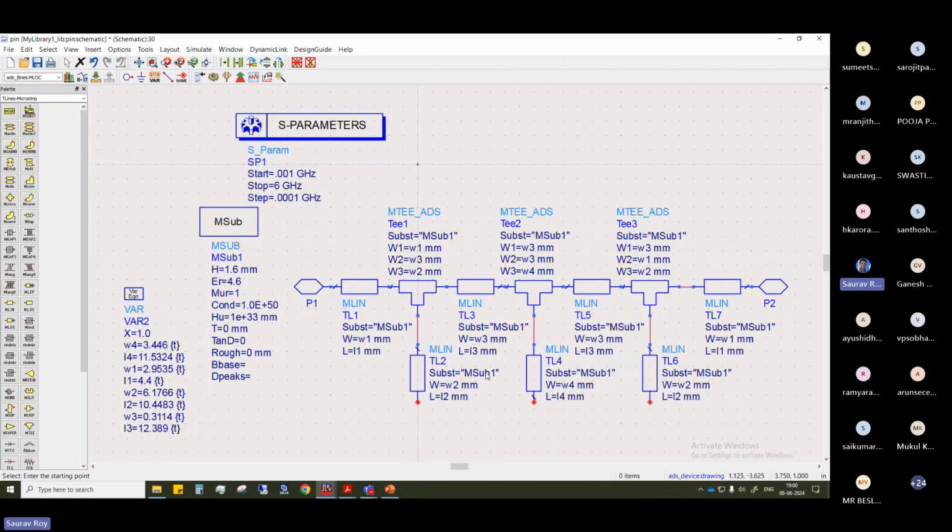There will be all these fringing components, so theory might not exactly follow. You might have a little bit of change here and there, so you have to do some tuning so that you get your cutoff frequency and roll off, whatever you want. But mostly it will follow. Okay. So yeah, that is the thing.